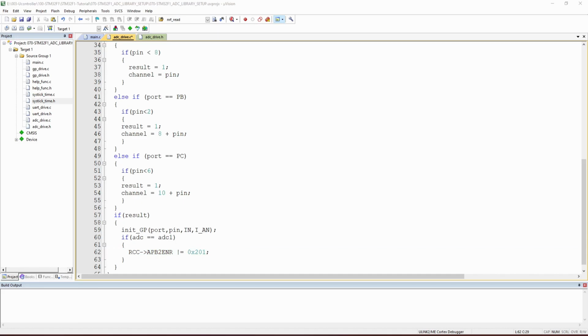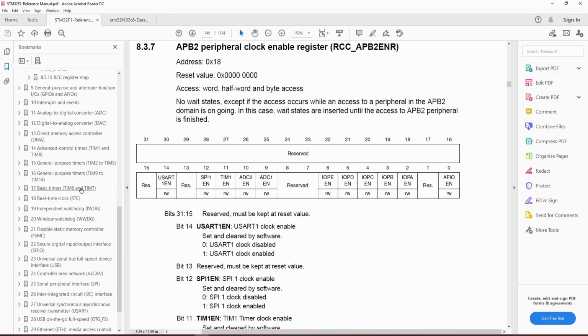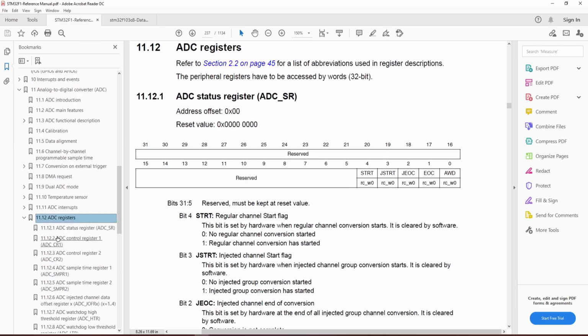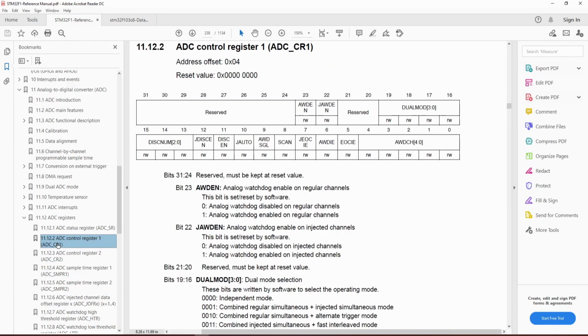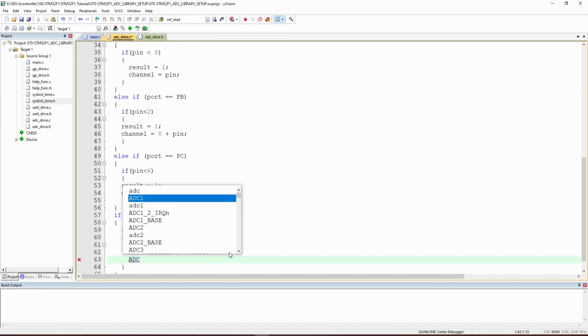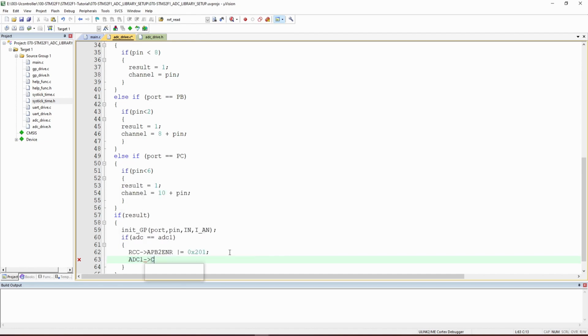So let's go to the ADC specific register. Quite very simple and easy for this ADC. So we jump here and we go to the registers. First of all, we have to set this register to 0, because there's so many setups here. We would like to put 0 here, so we are sure that in CR2, the control register, there's no extra setup. So what we can do is, actually, ADC1 CR2 is just equal to 0.